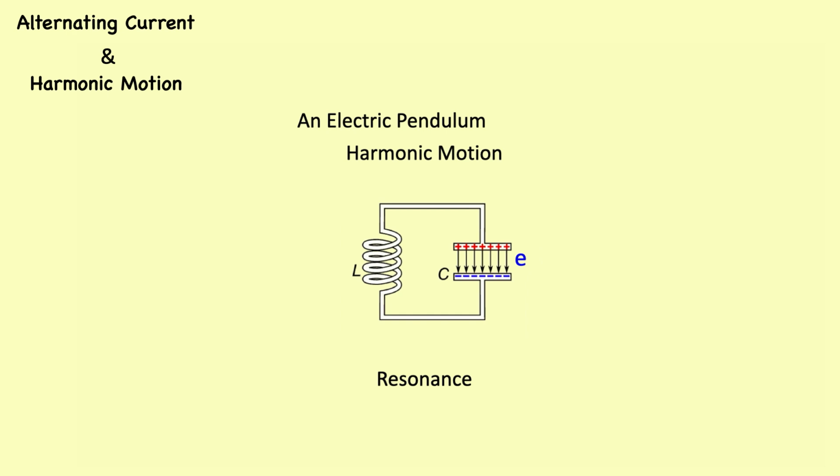However, this tendency to oscillate or resonate at a particular frequency is not limited to circuits exclusively designed for that purpose. In fact, nearly any AC circuit with a combination of capacitance and inductance, commonly called an LC circuit, will tend to manifest unusual effects when the AC power source frequency approaches that natural frequency. This is true regardless of the circuit's intended purpose.